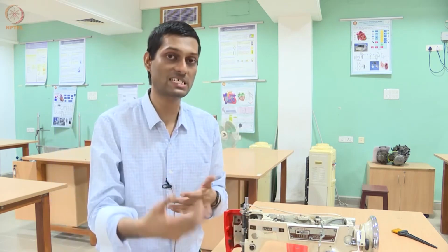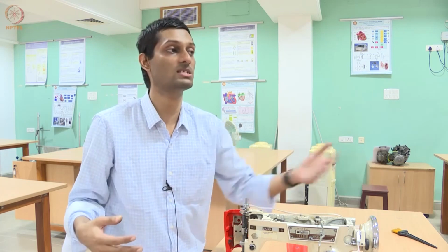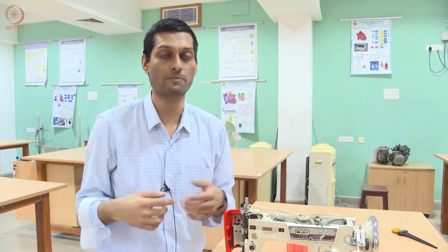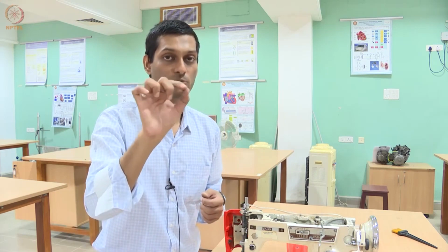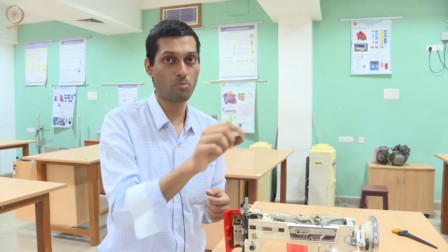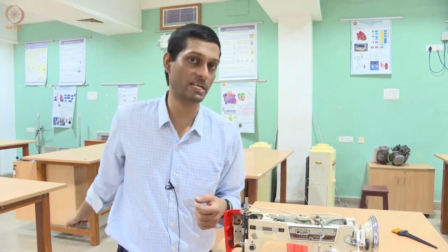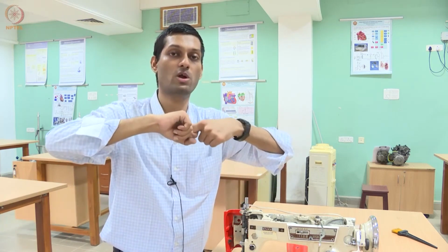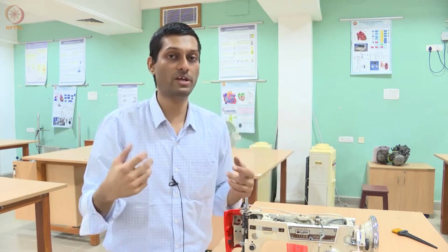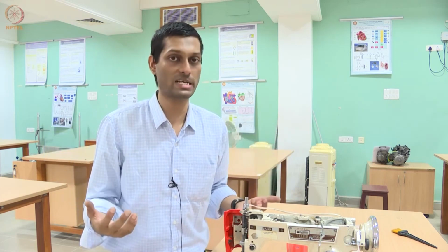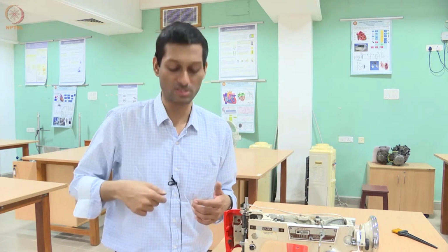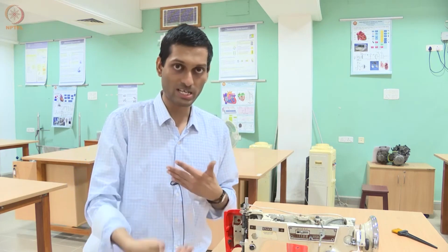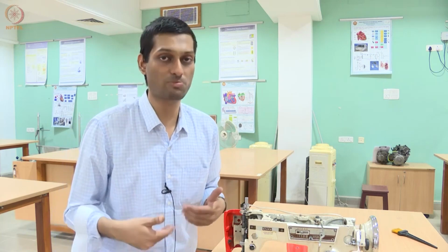If I were to cut one part of the stitch, the entire stitch will not rip apart, unlike a chain stitch, right? For instance, please go check out rice bags. The stitching they have there is different. If you just cut at the right portion of the thread, you can rip apart the entire thread just by destroying one part of the stitch. We don't want such a stitch in clothing. You don't want the clothing to fail. Even if part of the thread fails, you want the remaining part of the thread to remain intact. So lock stitching is preferred here.